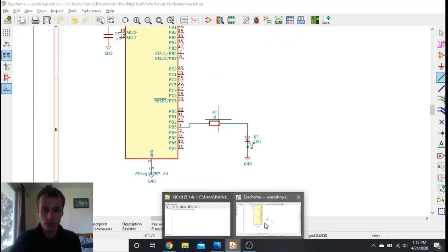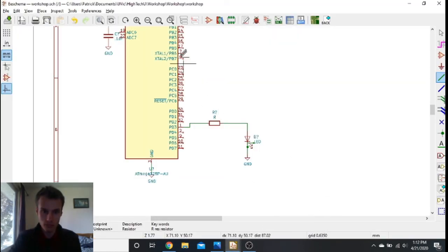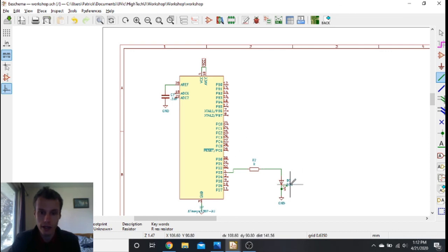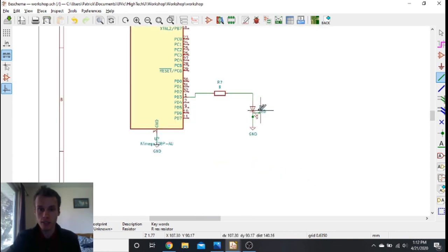So if we go back to here, for the Arduino Uno at least, and what we'll be doing, we'll be using 5 volts as the source voltage. We haven't decided where the source voltage is going to be coming from yet, but we know it's 5. So we have 5 and 1.8 coming from the forward voltage here, and we're trying to find a resistance that gives us 0.01 amps.